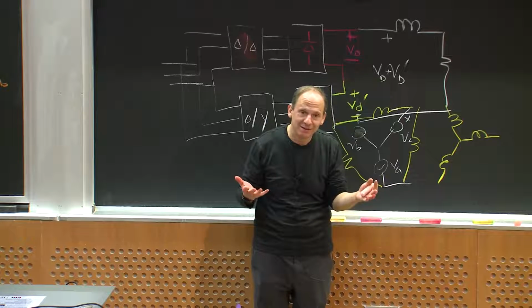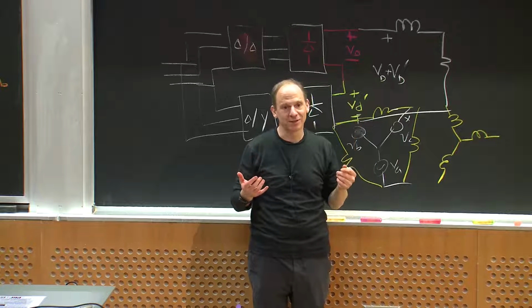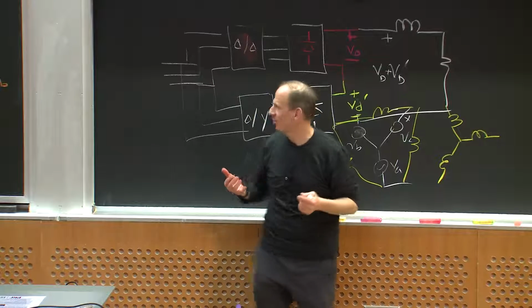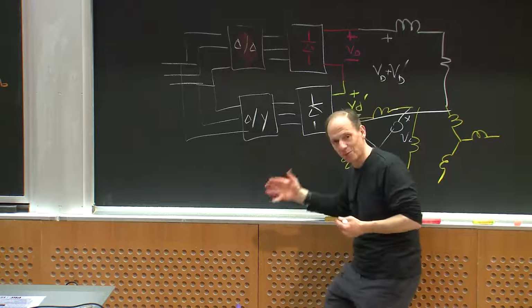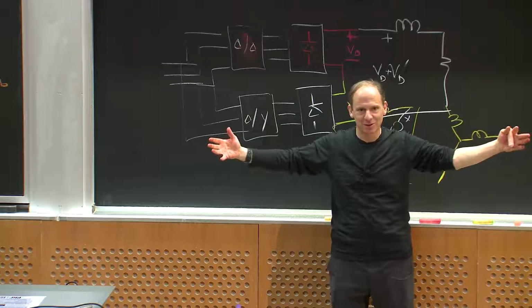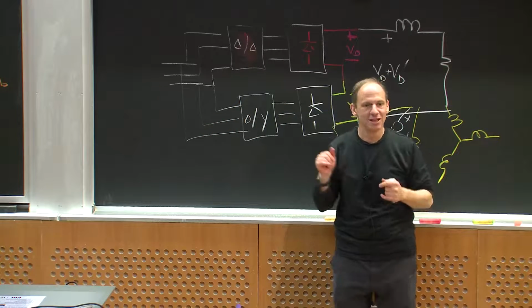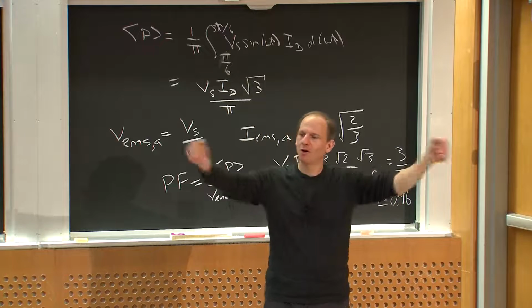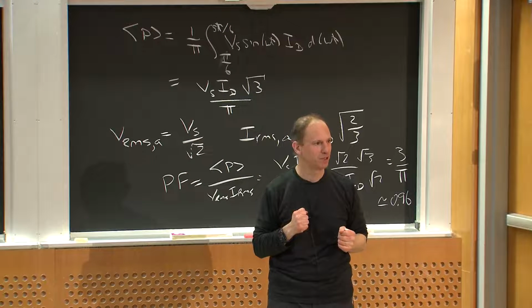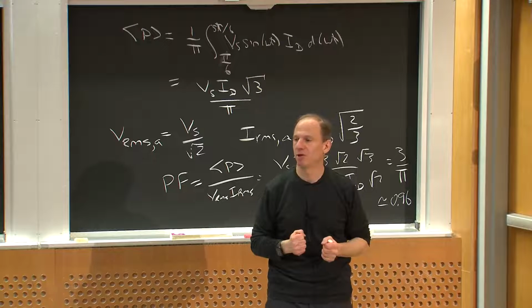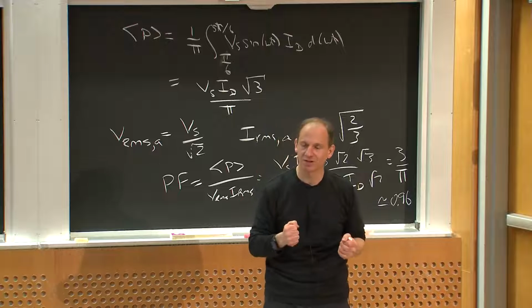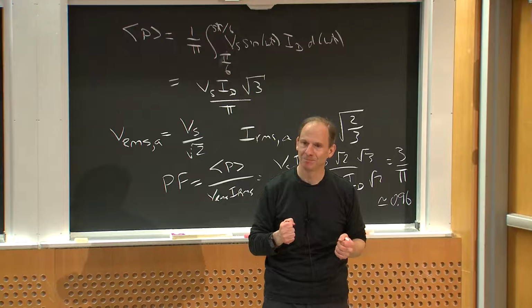If you don't like that, fine, do 3 of them, get an 18-pulse rectifier. People do that. You want a 24-pulse rectifier? It exists. What they do is use these phase-shifting transformer sets, stack them up in series or parallel with the right technique, and you can get to really high powers. Even though an individual diode is a nonlinear thing and draws harmonics, you eliminate all the harmonics and get something that acts beautifully. That's the game you play at really high powers with lower voltage and lower current devices than you could otherwise use, okay?